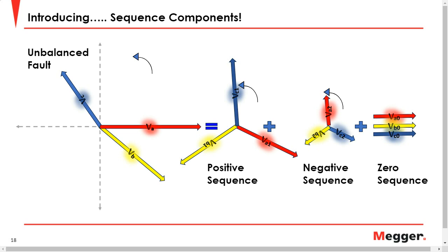What that means is that they end up circulating through the neutral, if there is any, because when you sum these 3, they come up with an amount through the neutral that is 3 times one of them. When you sum 3 things that are in phase, it's basically putting one next to the other, and that's why they say that triple order harmonics behave like a zero sequence component.